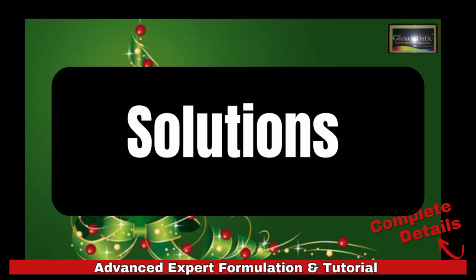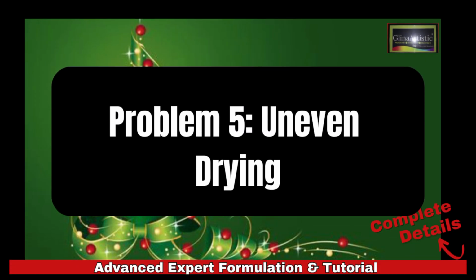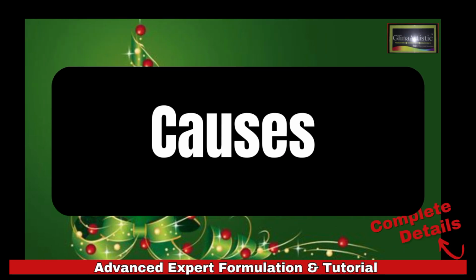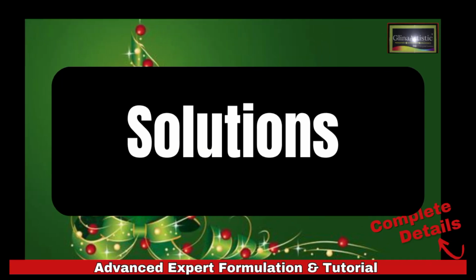Now, problem number 5: uneven drying. The symptoms are patches and uneven texture of finishes. So what are the causes? Improper solvent balance or environmental factors. And how to solve it is adjust the solvent to paint ratio, and ensure proper ventilation during application. That's when you're applying the paint.